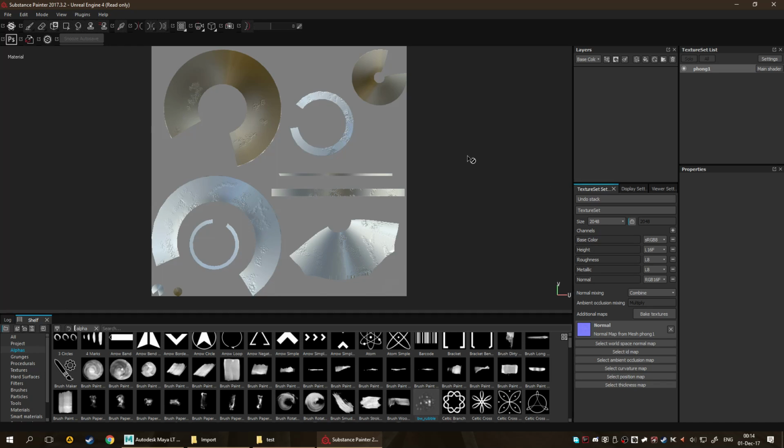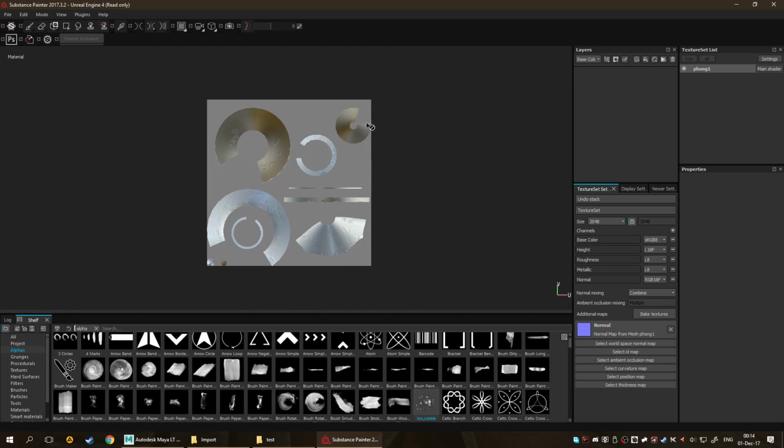Otherwise, they'll be U-dimension UVs, which is a huge pain in the ass to work with. Well, maybe not, but you're wasting space, right? Not space, but memory. It's a waste of memory. Certainly usable, if you really want to be a daredevil, you definitely can use it. But I think you'll be creating more headaches for yourself than necessary, since if you need more resolution, just increase the size of your map. And if you have to go higher than 8K, then you're probably in the wrong field, because higher than 8K, you're probably talking about movie level or CGI level of texture mapping, which is kind of overkill.